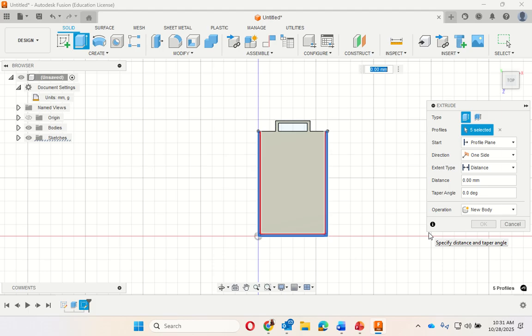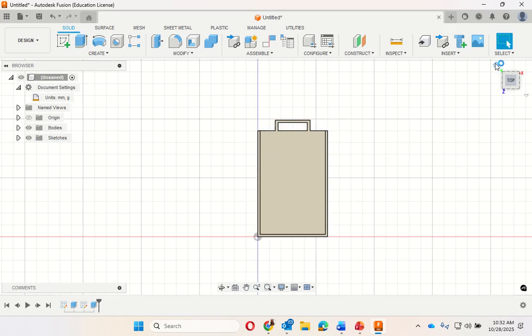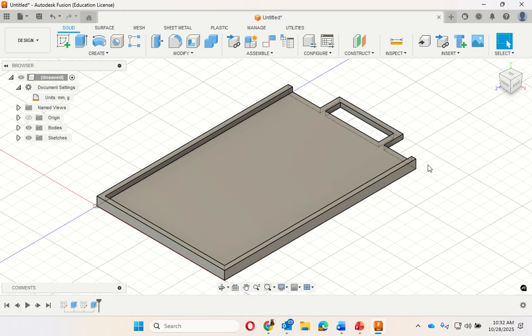Did you finish sketch first? Okay, you finish sketch, then you click on extrude, and then you go from there. So my distance here is also going to be 2 millimeters. And from here, I'm going to select that I want it to join. It needs to join because it all needs to be one piece. There we go. Now I could show you what it comes out to be. So now I have that groove in there.